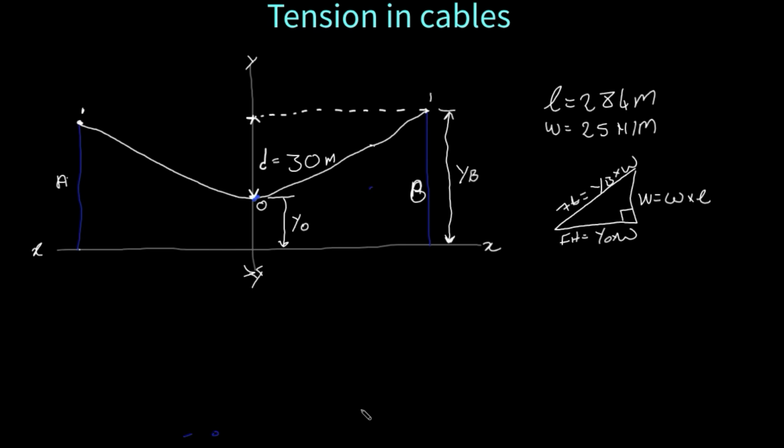So if we were to calculate the tension here, the distance of the support will be from the base or the reference point to here, which we can tell is smaller than the one on B. Therefore, it's going to be slightly smaller than the tension at the top of support B. The maximum tension will be at the top of the tower, which will be at the top of B, and the minimum tension will be at the turning point.